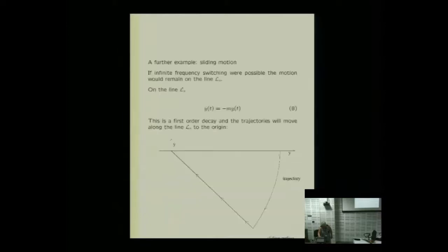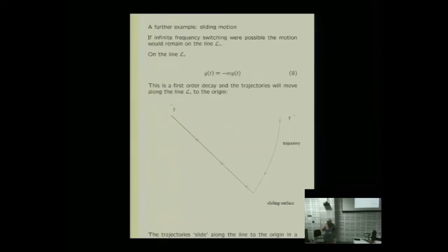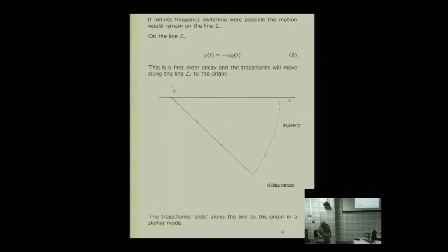So, here on my big graph, we see in detail what's happening in that ideal situation where our control effort is big enough, so we've got sufficient energy in the system to ensure that we can move. In this case, I think it was from y is 1, y dot is 0, straight onto the sliding surface. That clearly satisfies the constraint for m equals 1 that we had. And then it moves into the origin along the dynamics with the pole at -1, which was what I picked. And it's nice and smooth because I implemented it with a smooth control action.